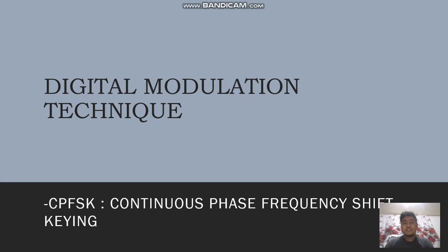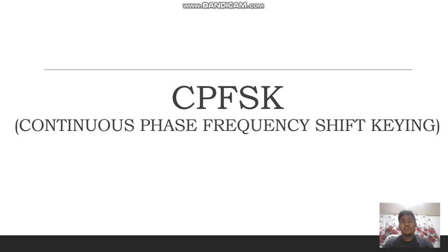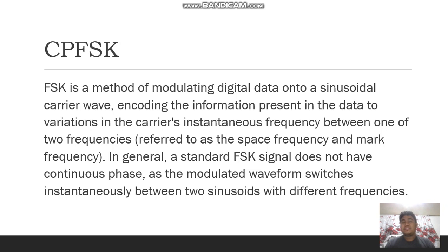Today's topic is all about digital modulation technique, focusing on CPFSK, continuous phase frequency shift keying. CPFSK is a method of modulating digital data onto a sinusoidal carrier wave, encoding the information present in the data into variations in the carrier's instantaneous frequency between one of two frequencies, referred to as the space frequency and mark frequency.